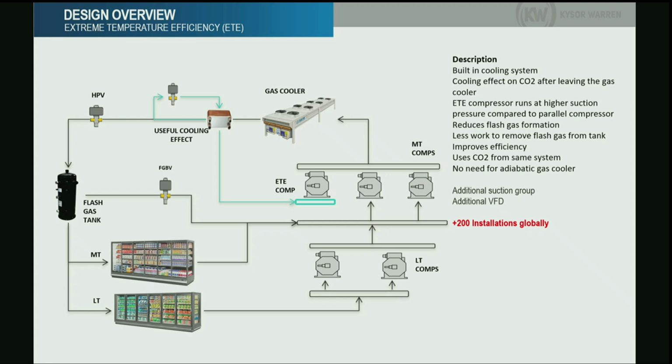So that suction, Ignacio, is coming from the plate frame. It's dumping into the common suction of the medium temp compressor? That's not a standalone? No, this one is a satellite compressor. Oh, it's a satellite compressor. Yes, it is. But it still dumps to the same discharge, right? Yeah, the discharge is the same, but the suction is different. It's a satellite compressor. You're at 650 suction.